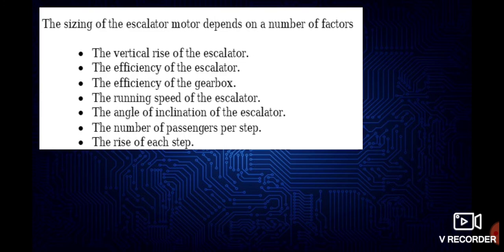And the sizing of the escalator motor depends on a number of factors: the vertical rise of the escalator, the efficiency of the escalator and its gearbox, the running speed of the escalator, the angle of inclination of the escalator, and the number of passengers per step. Also the rise of each step.